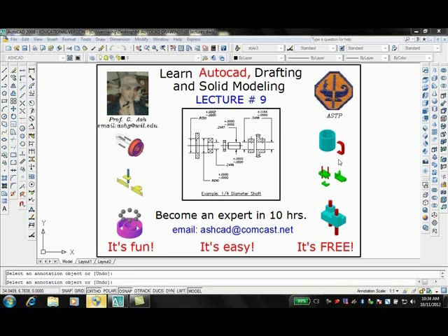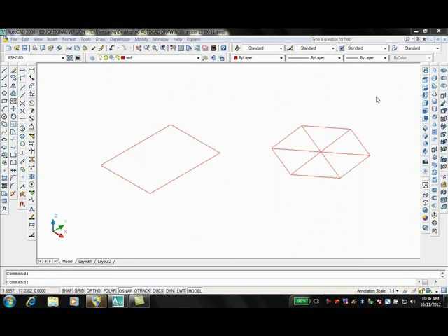For now, I'd like to get started with an example of AutoCAD's 3D face command. The simplest form of a surface in AutoCAD is a 3D face, which has no thickness. But 3D faces are flat surfaces with 3 or 4 straight edges.